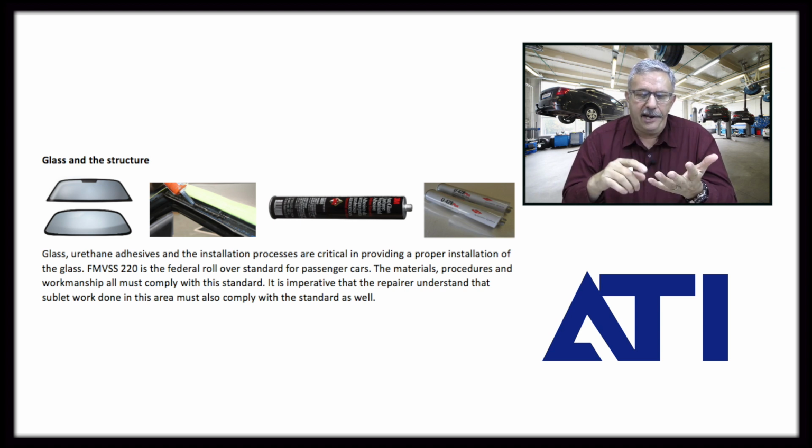The other things that are important here are how are we putting the glass in, who's putting the glass in, and how long has it cured before the vehicle goes out into the weather, because it says very specifically 24 hours at an ambient temperature of 72 degrees, and it gives a parameter of the temperature. So we may need to look at in the future whether there is stall tie-up time that should be charged into the estimate as well while the urethane cures. Again, that's not something for today's topic, but that is something that we're going to be looking at in the future.